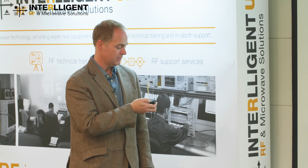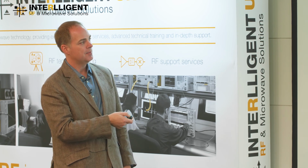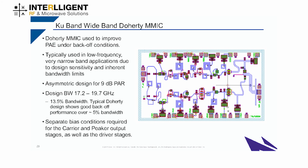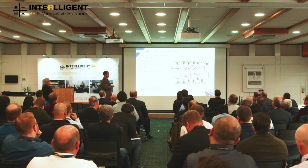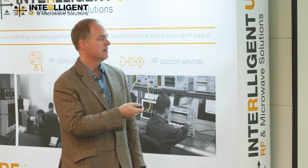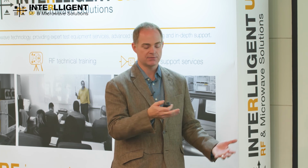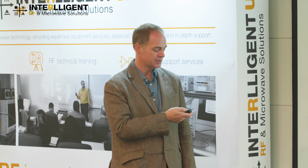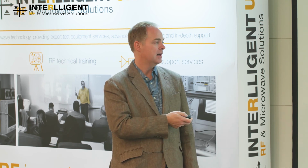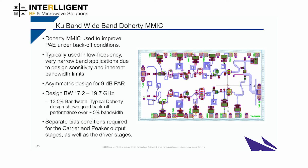But in any case, with this design, I should mention that it is an asymmetric Doherty, so you can see that we've got a 2-to-1 ratio for our peaker and carrier amplifiers, and that's to achieve a 9 dB peak to average ratio in the design. This was actually a 17.2 to 20.2 design. There's a little bit of roll off, but over the 2.5 gigahertz of bandwidth up here, we did get 13.5% bandwidth, which is much higher than you typically expect to get out of a Doherty. That is one of the key trade-offs, efficiency versus bandwidth. And this does have different bias conditions, because you need to bias both the peaker and the main carrier amplifier at different conditions. One's Class C, one's more of a Class AB.